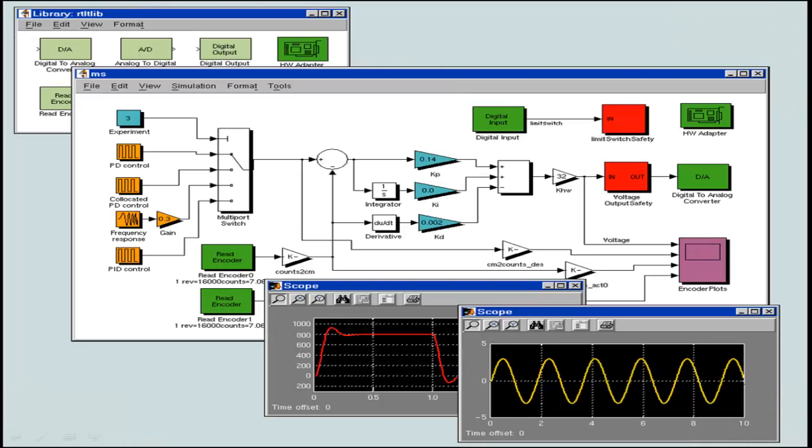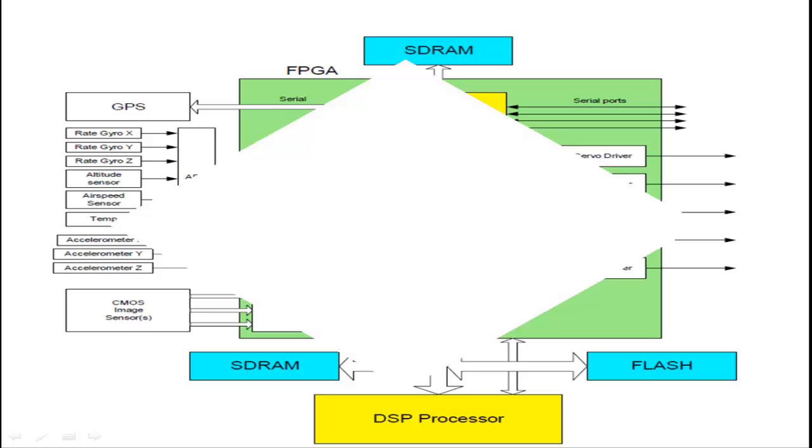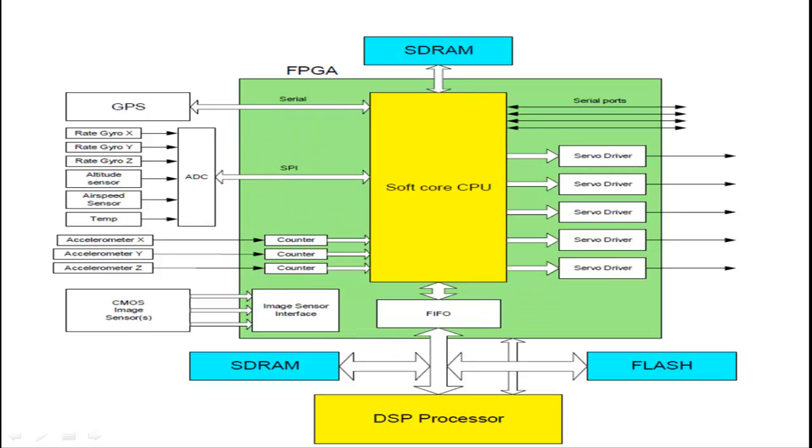From what we can see in this picture, the system starts to work by designing the desired circuit in Simulink and doing the simulation. After that, the data from Simulink is fully integrated and interfaced by the FPGA through the serial ports, and the data is automatically saved in the memory in the FPGA. A separate microprocessor works in order to make the system run smoothly. By that, it will process and convert the data into hardware to run all the components in parallel, including the control of servo to all parts of the control surface system.